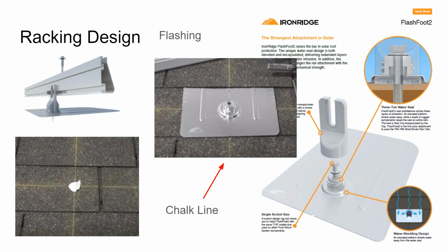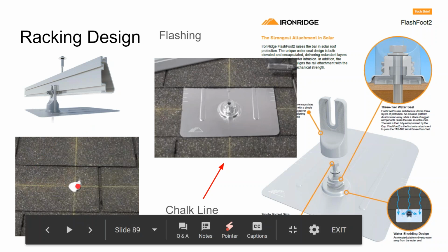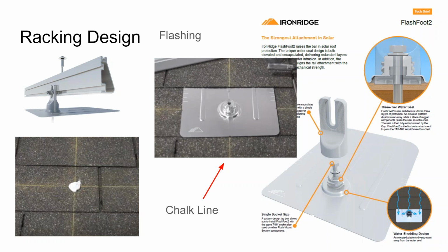And so what I'll do is I'll go across the roof and bang the roof, and I'll take a whiteout marker and dab the roof wherever I think there's a rafter. I'll start at the top and do it in 3 different spots, at the top, in the middle, and at the bottom, and then look at my spots and see if from one row to the next they're lined up or not. And once you get going with it, it kind of falls into place if you know your rafter spacing.